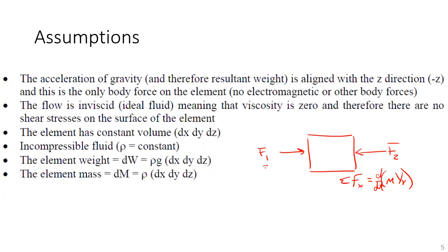If we have viscosity and you have velocity changing within the cube, and you will actually be measuring this in one of your labs, that velocity does change the further and further away you get from a wall of a pipe. Then you would necessarily have shear stresses all over the surfaces. I've just drawn the ones in the x direction that are on the dx dy face.